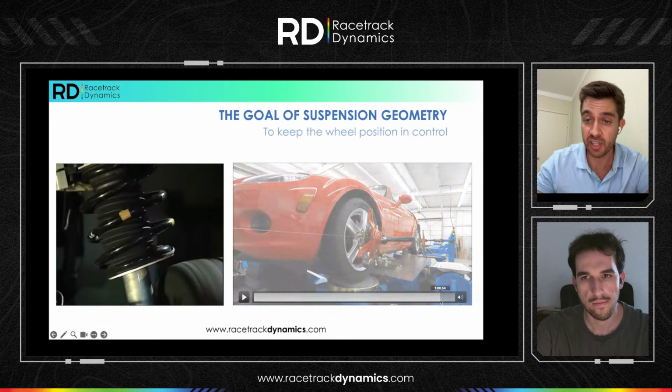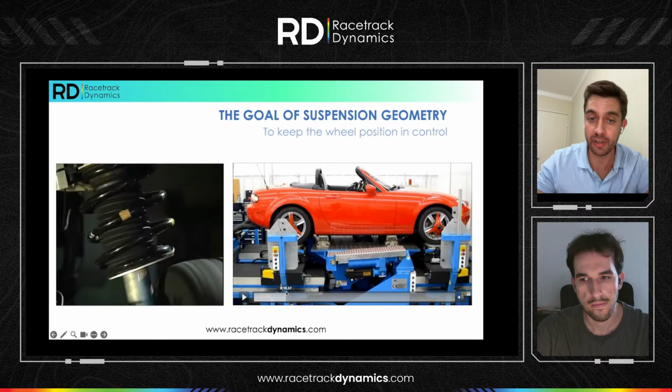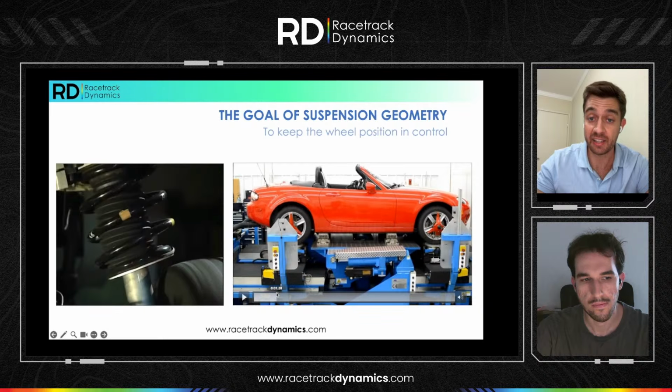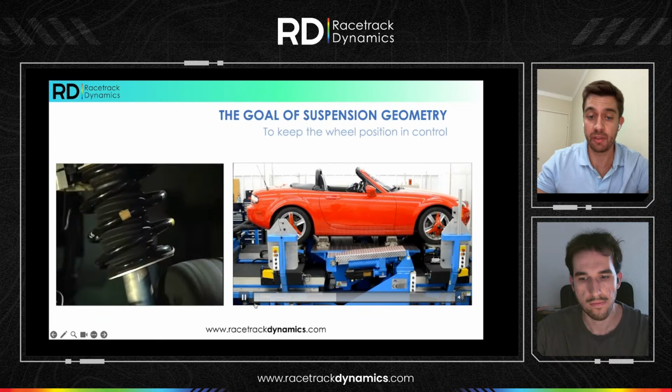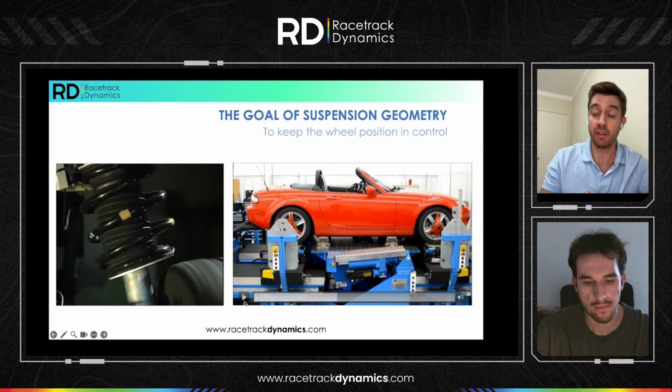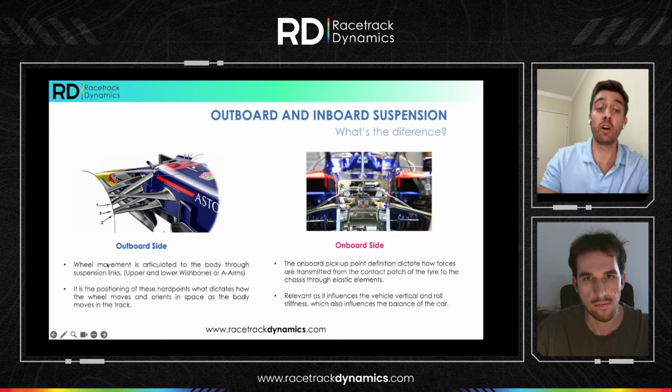And can you see as well, maybe it's a bit more evident here, how the rear wheel is going forward and aft? It's moving in the x-axis of the vehicle as we impose this vertical motion. So all these movements of the wheels are going to be dictated by the outboard suspension of the car. We'll see that in a moment.